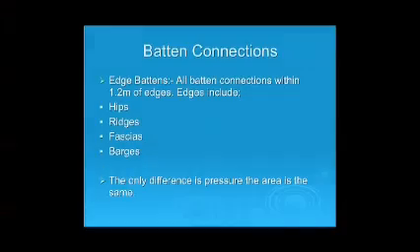So this is very important. I'll get you to write this down. Batten connections. Edge battens are all connections within 1.2 metres of the edges. Edges are not quite what you think. Edges are hips, ridges, fascias or barges. So I want you to record this, please. It's very important you get that embedded in your head. The only difference between the two